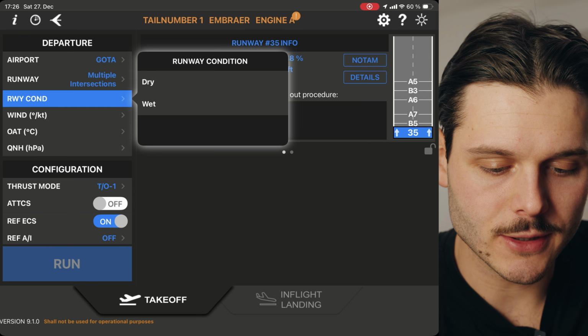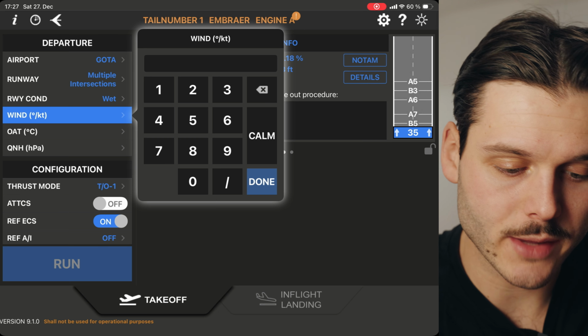So the runway is dry or wet. With our program, we do have more to choose from. We also have a condition code of 6 different parameters. 6 is dry, and 5 is good. And below that, we have different kinds of condition codes like slippery and snow, compacted snow, how many millimeters, and all the information is given in the ATIS, the Aerodrome Terminal Information Service, and we then put the information, sometimes also with a matrix that we have in the quick reference handbook, into the ePerf to calculate the takeoff performance.